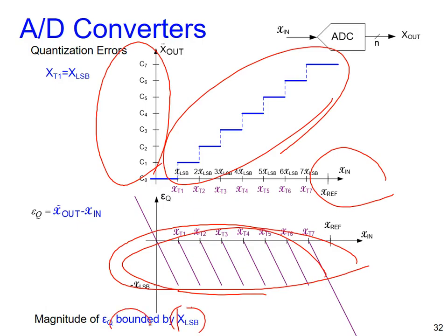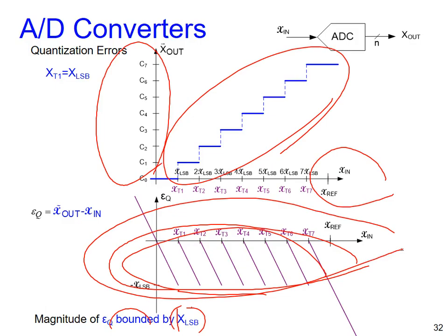Intuitively, it doesn't make any sense. Even though the ADC is ideal ADC means no error. Sorry for that. Under such kind of situation, even though you have ideal ADC, you still get maximally one LSB in error. Wow, it is hard to understand. Why? Ideal structure, ideal circuit still get such kind of very huge error.